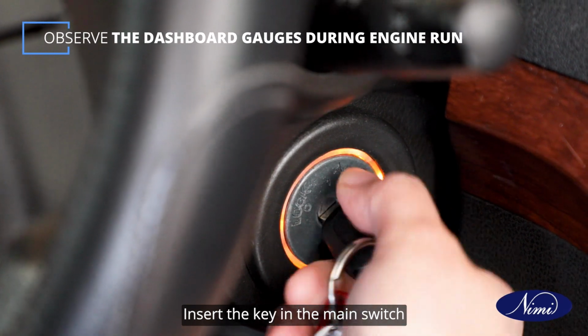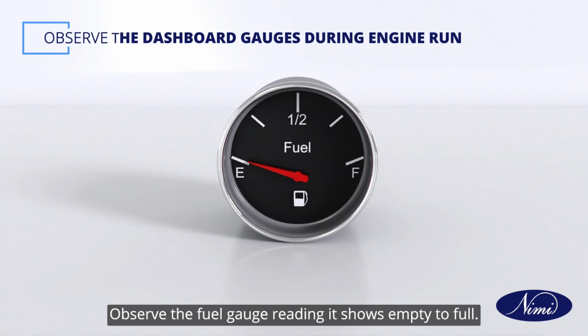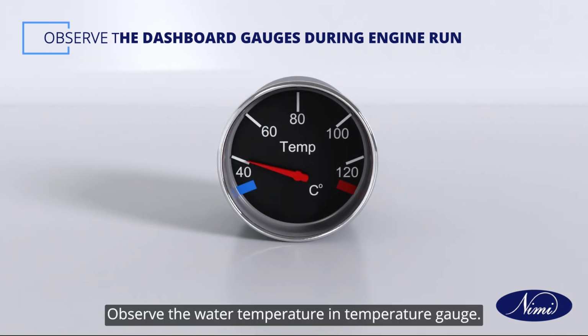Insert the key in the main switch and turn the key to the on position. Observe the fuel gauge reading. It shows empty to full. Observe the temperature gauge reading. It shows minimum temperatures. Observe the oil pressure gauge. Observe the water temperature in temperature gauge.